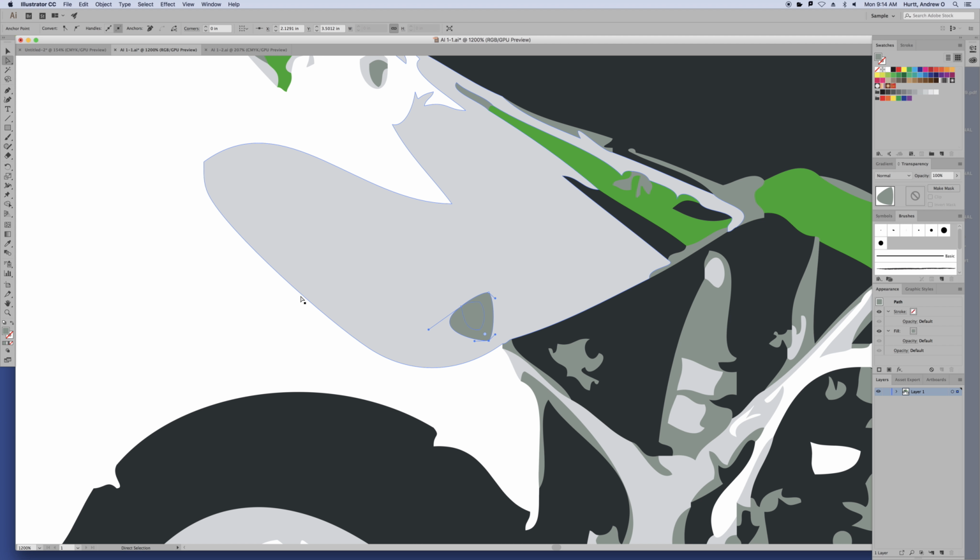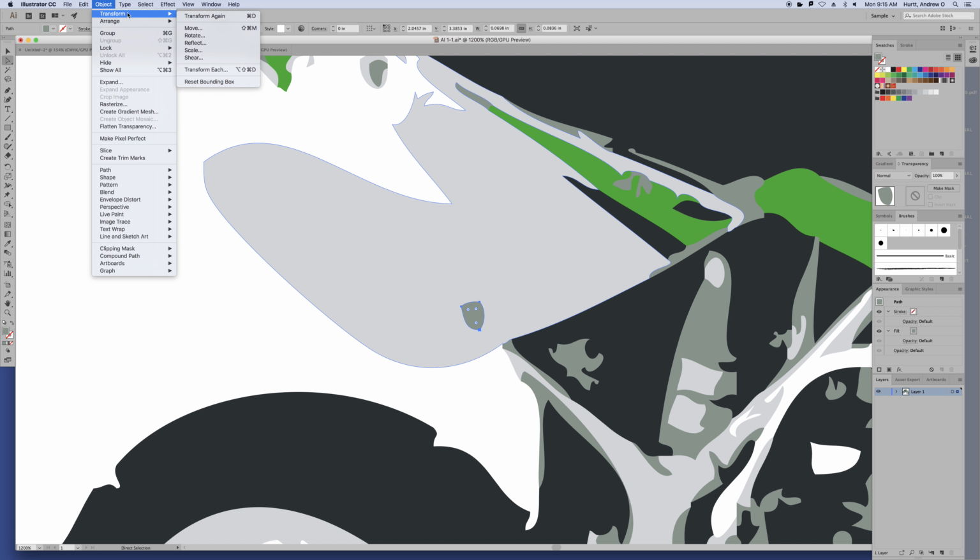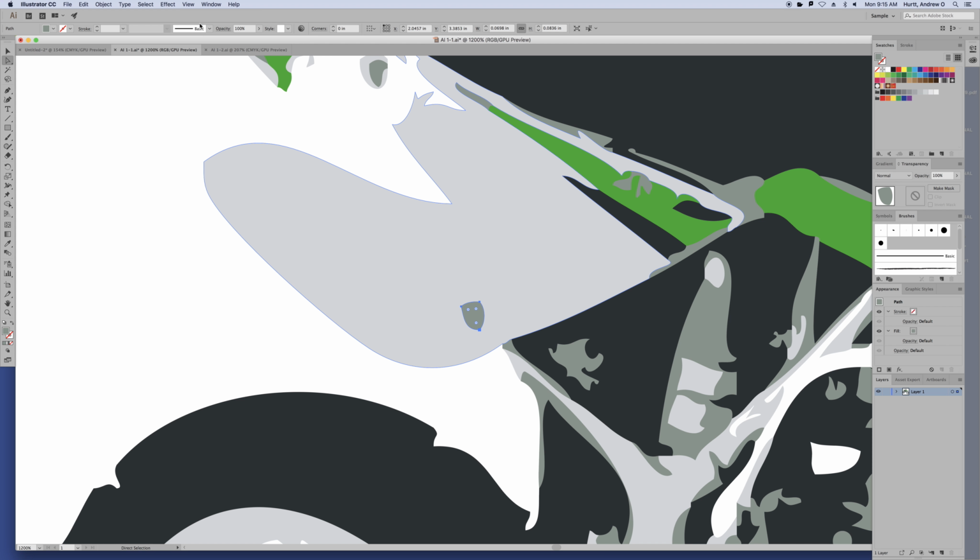A trick that I do, let me go back so it's the original. There we go. Go back to the original shape. I'm going to transform, arrange, bring to front so it's on top. What I'll do sometimes is I'll direct select and click essentially in the middle of the object so I have all of the 3 points selected. And then I'll go back to my selection tool, and now it'll allow me to resize this object and constrain the proportions.